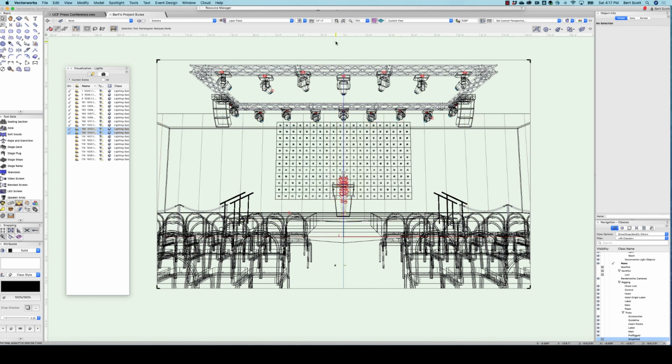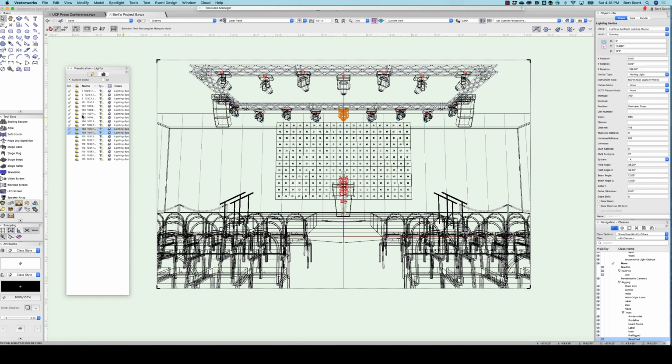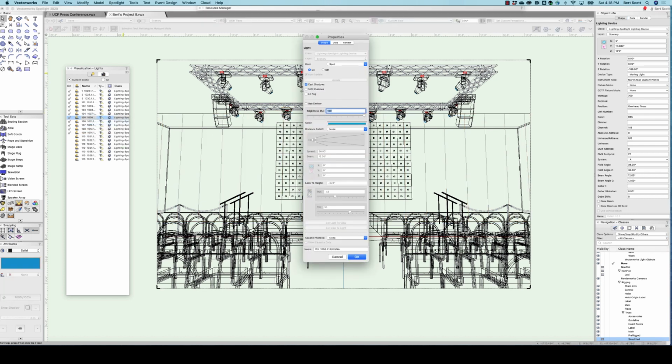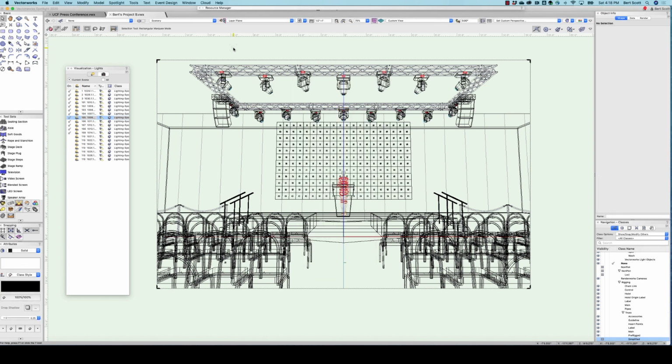And I think in my rendering, actually, I have the center one on as well. So that's 1, 2, 3, that's 105. So we're going to edit that and turn the fog on. All right, getting closer. There's a second step to the turning fog process on, and it has to do with the way the light interacts with the background of the rendering. Even though we can't see the background of this rendering because we're inside an enclosed building, we still have to turn the fog on in the background.